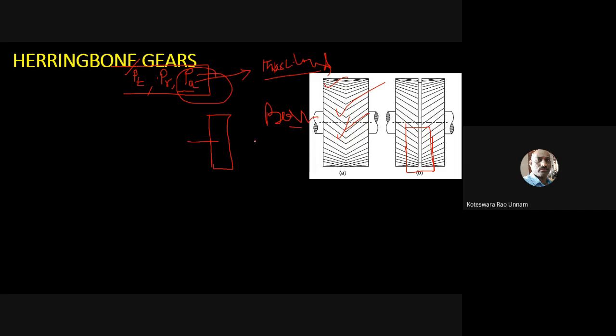Because your spur gear teeth are cut parallel to the axis, you have only radial and tangential components of forces. Since the teeth are parallel to the axis, the bearing here, or maybe somewhere else, is not going to produce any axial reaction in this direction. Now, if I take a helical gear which has a single helix, single hand, that is either left hand or right hand, something like this, because of this helix angle it will produce axial reactions or axial forces on the